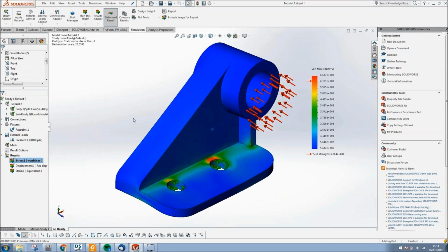You can see here some of the other nice features of SolidWorks at this point is that through the connections module of the simulation study, it's detected automatically that this body, whilst it's a different body to the part that we started with, it's completely adjacent, and it will tie that into our simulation. And that makes the whole process much more streamlined for what we're trying to achieve here, which is to reinforce the part.